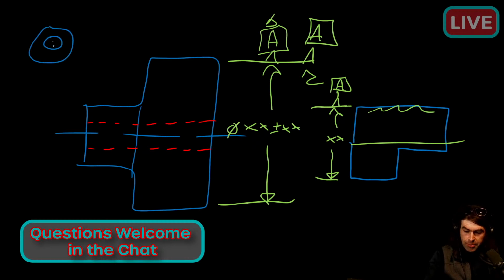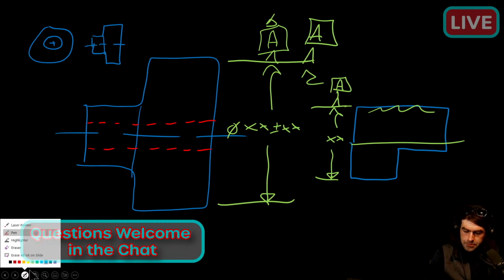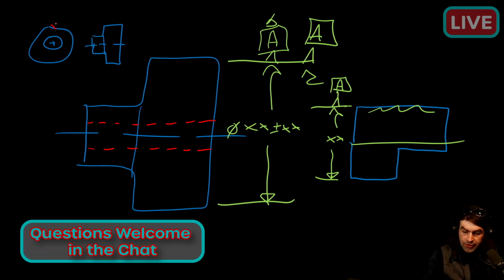Say you have a part like this right up here in this corner. The designer could specify, hey, I want line contact on these 3 spots, right? And they would call that out with datum target symbols.